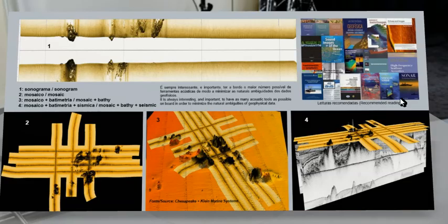I also finished the book showing some interesting books to read about Side Scan Sonar, about acoustics in the sea, and also reinforcing the point that it's very important to use side scan and bathymetry to have a 3D view, and also sub-bottom profiles to see how deep the bedrock goes that you're watching on the surface. So to work with these three tools simultaneously is great. It's always the best solution for any project.